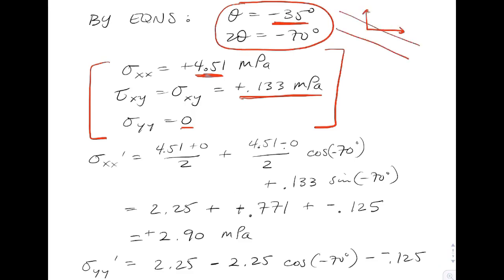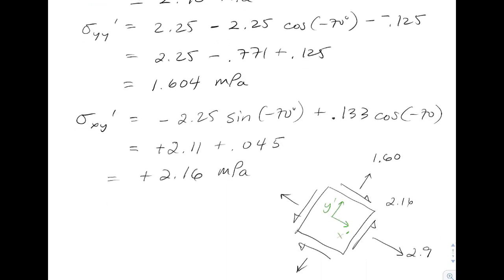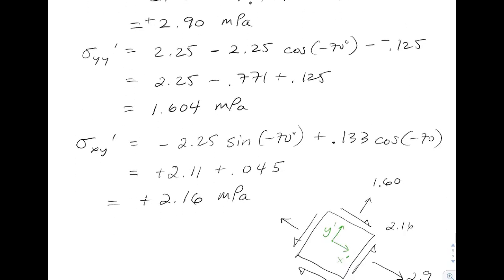The grain was at this angle, so we would want to take and align the x prime axis. So this would be a negative slope on the x prime. So we would use negative 35 degrees. And from there it becomes a plug and chug, hopefully not making any calculation errors, but you would end up with the same answer. Not much recourse though, if you do make a calculator error.